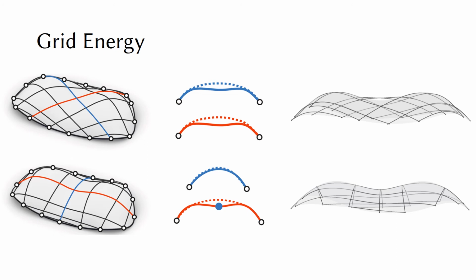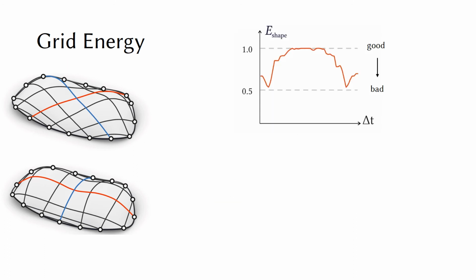The main aspect of our work is finding networks of curves that nestle to the surface well when boundary conditions are enforced. As evident, some grids are better suited than others, and their choice obviously depends on local surface features. To this end, we introduce 2 energies to find a suitable layout. To ensure a close approximation of the target surface but avoid costly physical simulation, we introduce an energy that estimates how closely a grid will preserve its initial shape when boundary conditions are enforced.